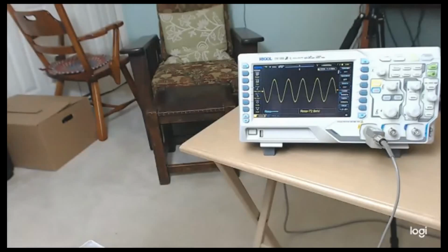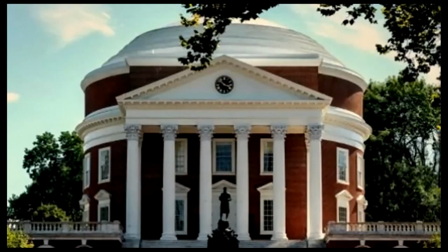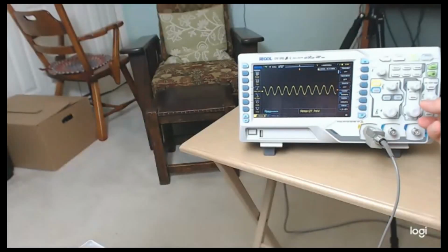It turns out the DDSs, if you're really careful and sneaky, there's like a secondary alias mode that's like a harmonic, and you can actually go like double the frequency. You can, and this module actually has the filter on it, so that's what's keeping everything nice and clean there. So that's at 20 megahertz right there. Let me go up to. All right, so that's at 40 megahertz, and you see it's starting to get a little squirrely, and not as clean.